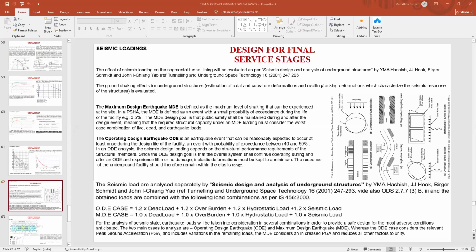So in the MN curve also, we are putting partial factor of safety against concrete and steel. We are putting partial factor of safety against our ULS loads also. So this partial factor of safety is very important to take into account all your uncertainties. And that is why you see in Eurocode 7 and Eurocode 2, we are putting partial factor of safety on material, and we are putting partial factor of safety on loads also.